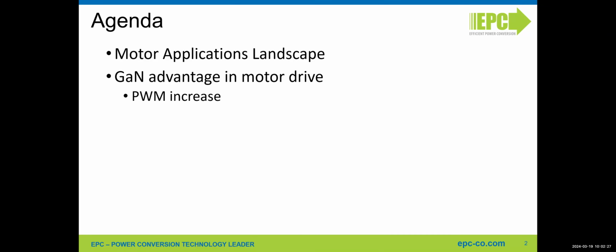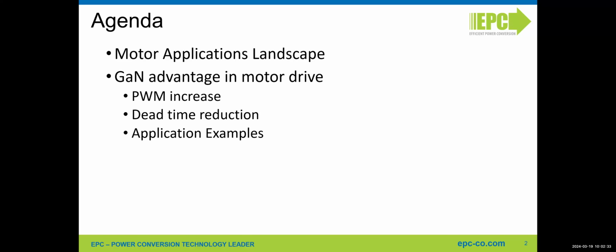What you can do: you can increase the PWM frequency, you can reduce the dead time, and then I will go through some application examples to show the effect of using a gallium nitride inverter in motor drive applications.